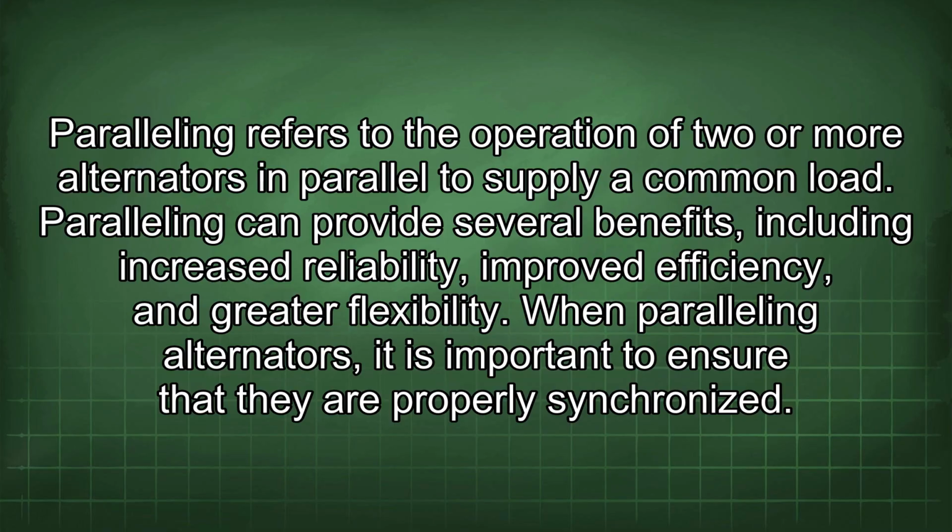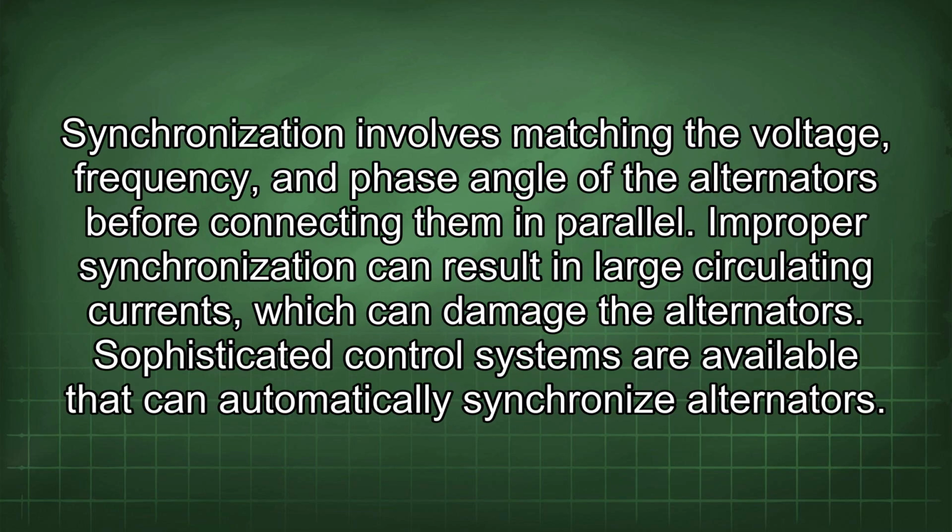When paralleling alternators, it is important to ensure that they are properly synchronized. Synchronization involves matching the voltage, frequency, and phase angle of the alternators before connecting them in parallel. Improper synchronization can result in large circulating currents, which can damage the alternators. Sophisticated control systems are available that can automatically synchronize alternators.